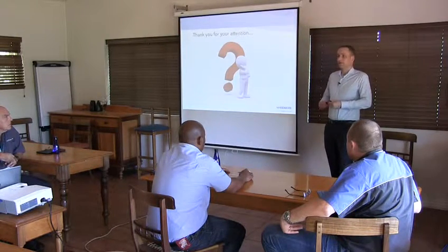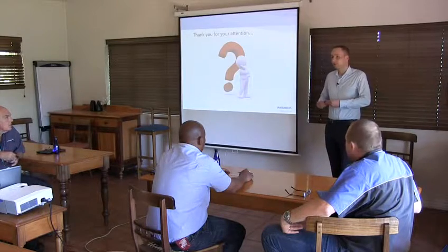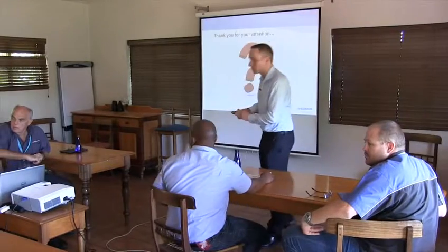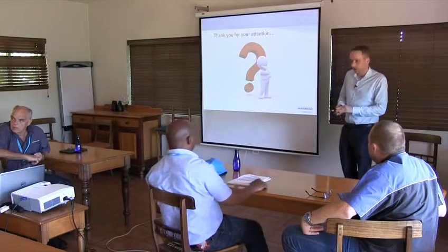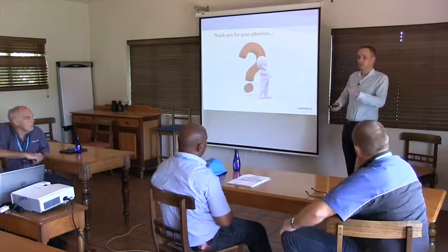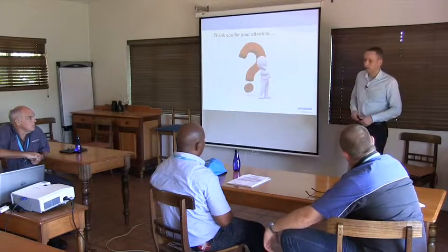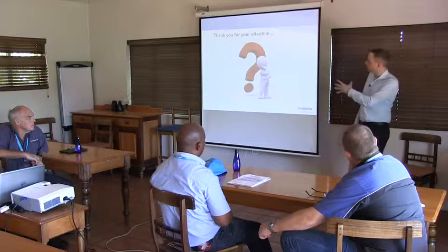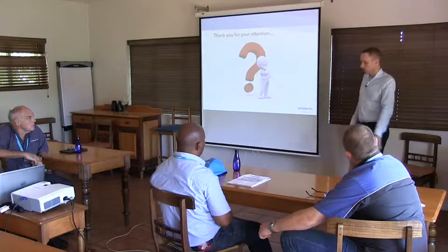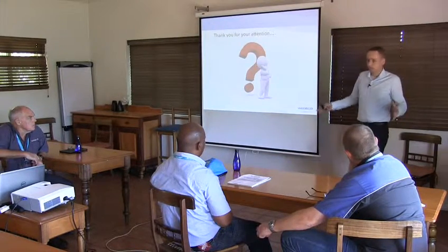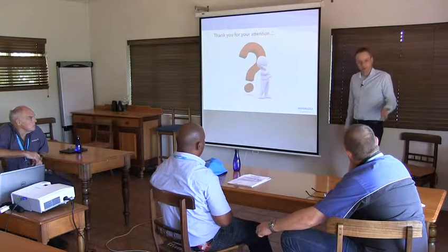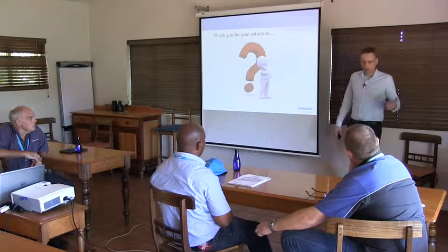You prefer medium pressure? Sorry, I didn't understand. No, medium pressure is polychromatic light, and there you have the problem that you're putting a lot of power in the water. The normal low pressure lamp, for our bigger systems, has a UVC output per lamp of 150 or maximum 210 watts.